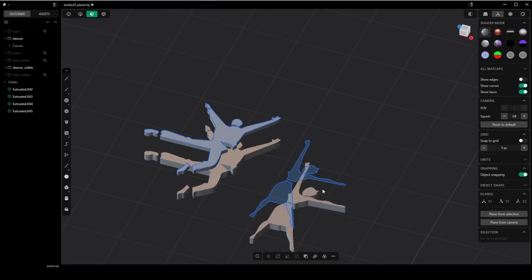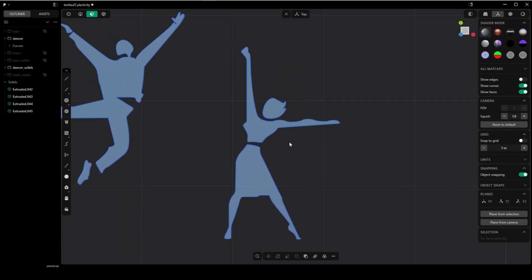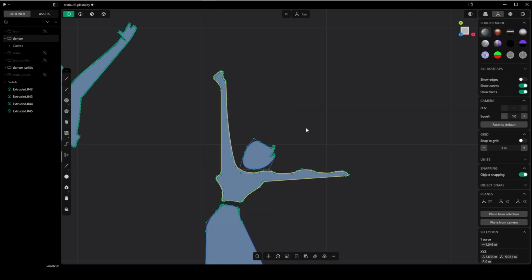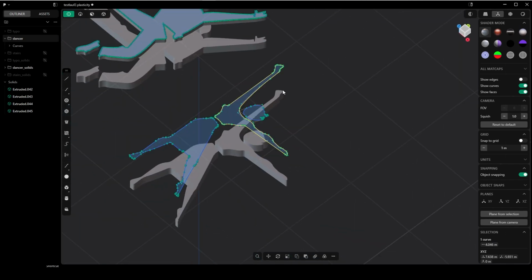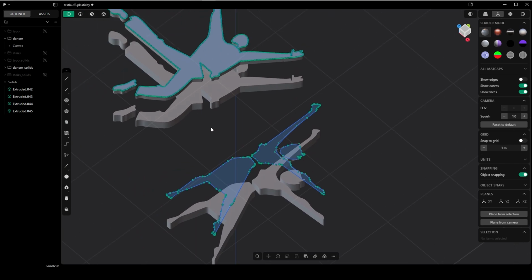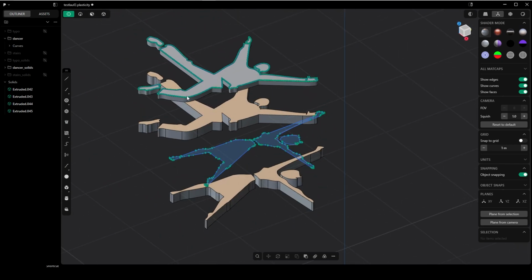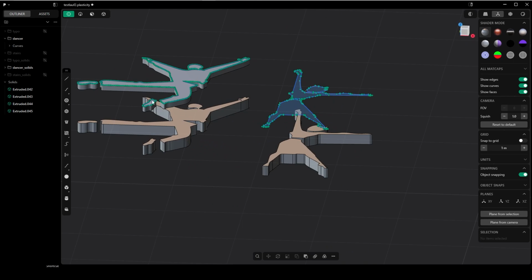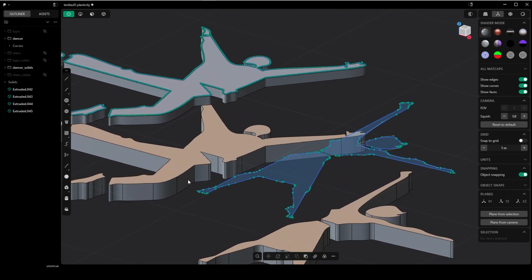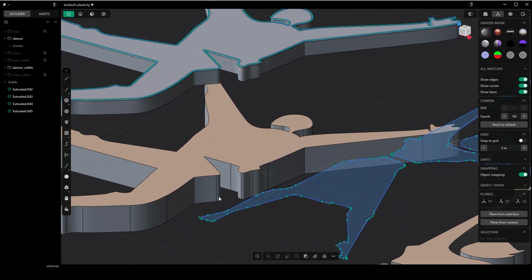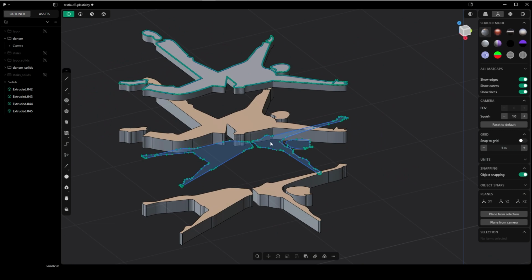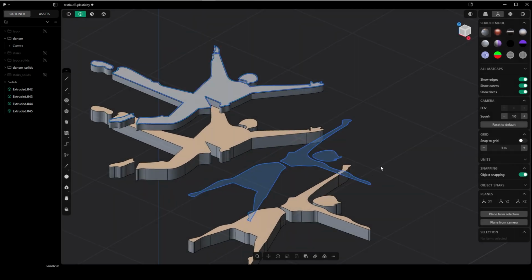Alt H, bring back the rest. Let's look from the top view and select in control point mode, rebuild. And by the way, let me show you one more thing concerning the rebuild stuff. The rebuild, as I showed, gives you a much cleaner result without any unnecessary edges which cause drama when you try filleting. The second thing which the rebuild with the points method does, it merges the curve. Let me show you what I mean.